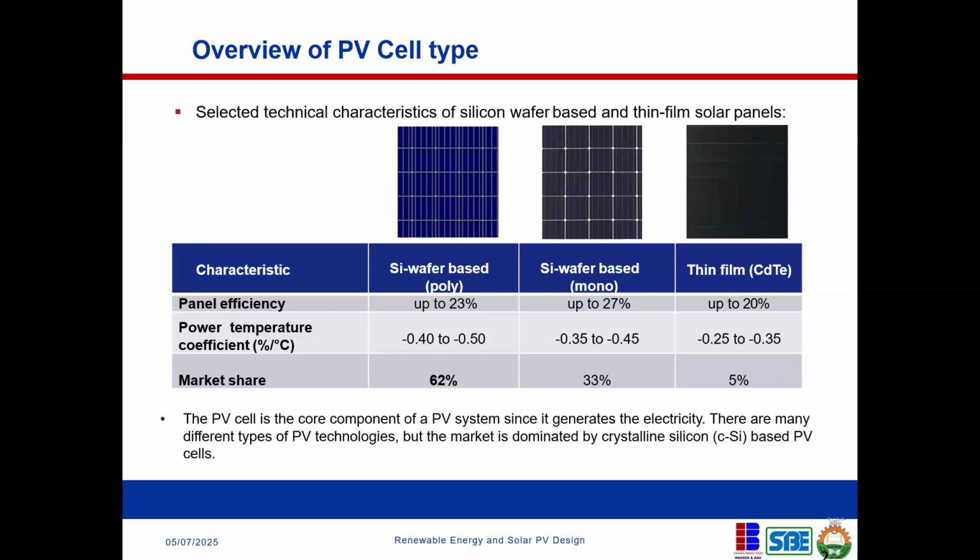But now, because of the cost competitiveness becoming stiff, you have more of monocrystalline, and their efficiency has also been improved a lot across both polycrystalline and monocrystalline. But as the market stands today, if you look at the cost difference and the efficiency gain, in most cases, you want to go for the monocrystalline.